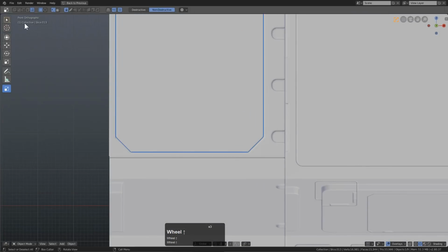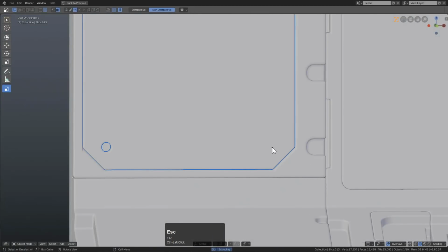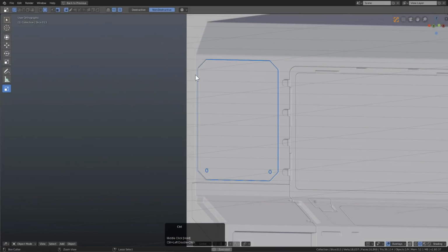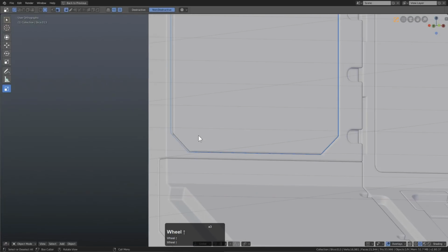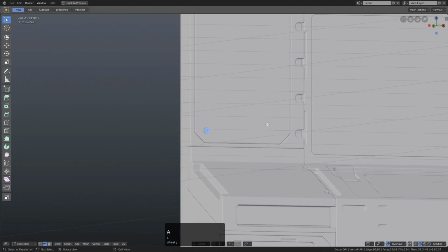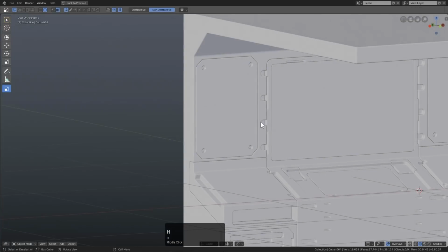But you know, for example, having circle automatically jump to center was critical to me, because I want to be able to select circle, and right here I was about to repeat the shape here by just control left clicking, which I guess I could do that, call it a day. But really, the thing could be solved at the level of this circle, right? I'm going to draw a circle, bring it in, hold shift, keep that thing. We're going to clean the mesh because I hate seeing all the points converge in the center. But now we can duplicate this over, select this, duplicate it up, and we have our holes here.